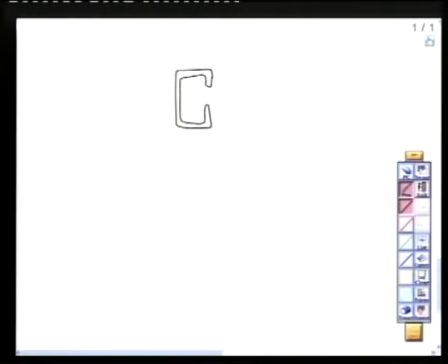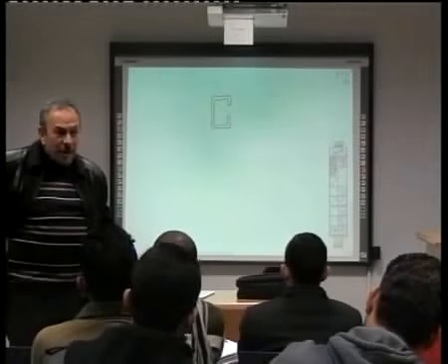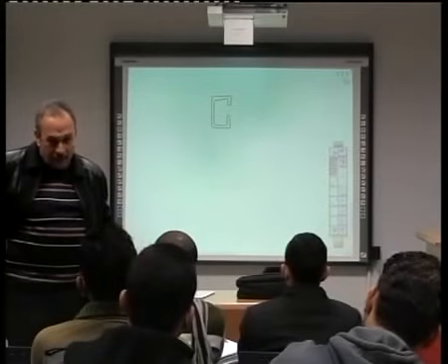Now, he was unable to do classical solutions, so the one who helped him subdivided the deformations into axial, shear, moment, and torque. And it turned out that the torsional deformations are hundreds of times more than the others.